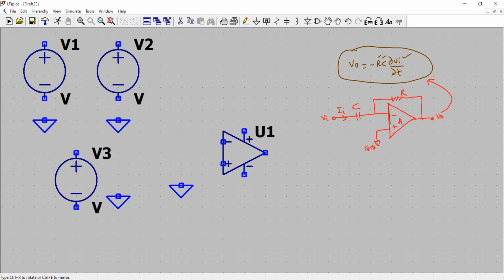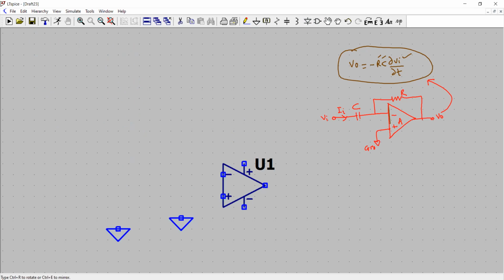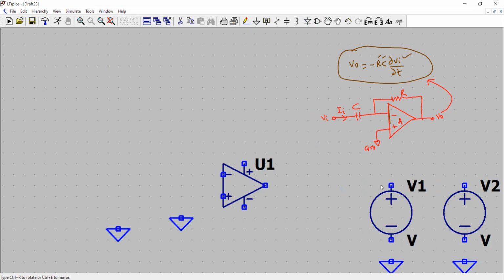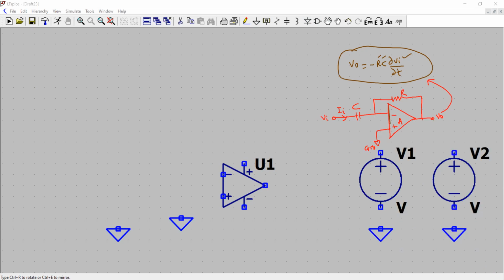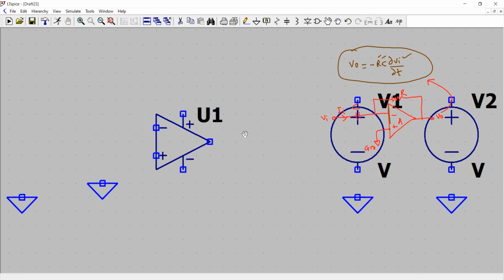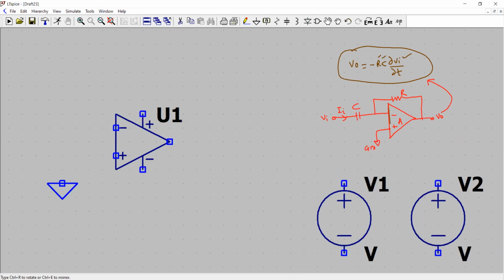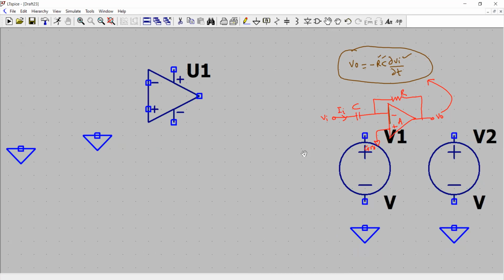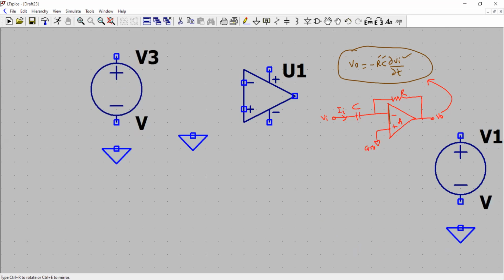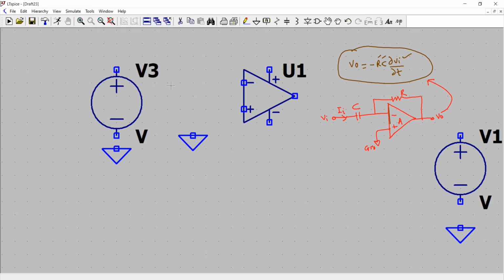signal. So now I don't have a place here. So let me just adjust it. So I will just select move, and then these two components, I will place somewhere on the right side of the screen, and then I press the space bar on the keyboard. So again, I am having trouble seeing the complete schematic. So let me place them somewhere at the bottom. Now it's better. And now I will just press F6. That helps me to copy the components and the devices. So here I have placed that.